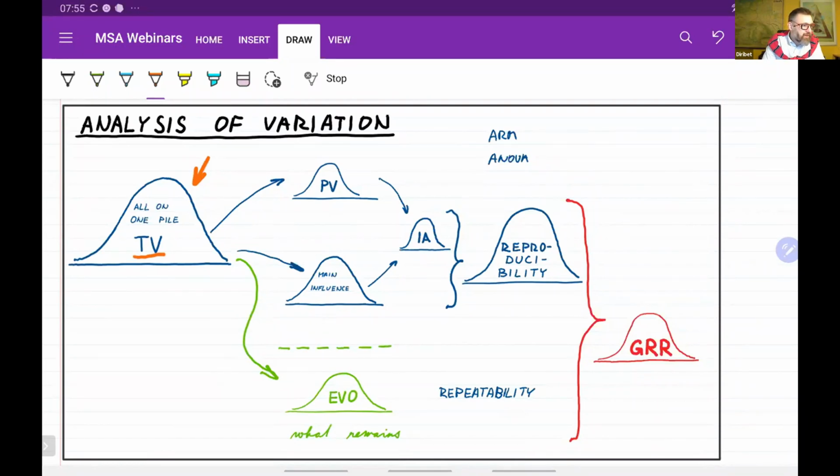And in the measurement uncertainty, we make the assumption that the measurement error has a mean value of 0. That is an assumption, even for bias and things like that. It has a normal distribution, so we are left only with one parameter, and that's the standard deviation, or as we call it, standard uncertainty in this context.